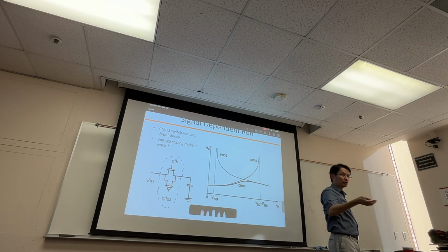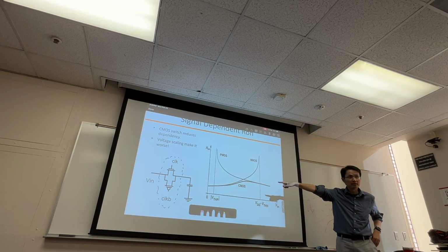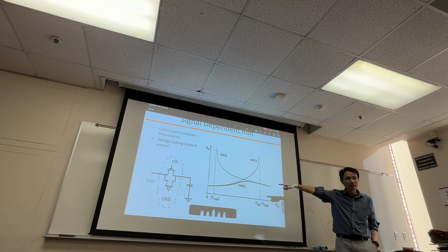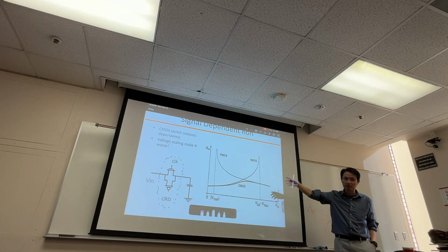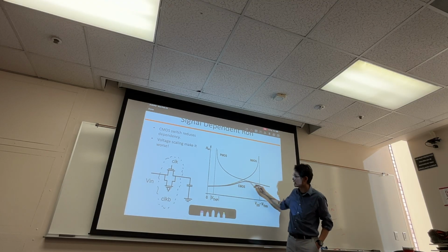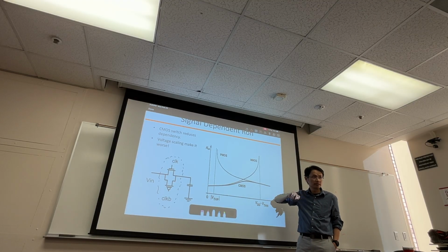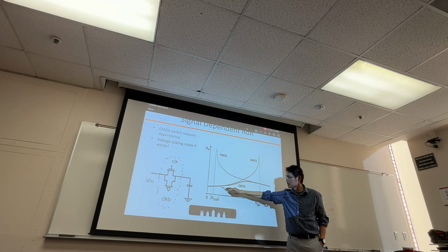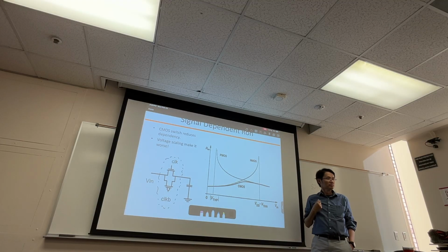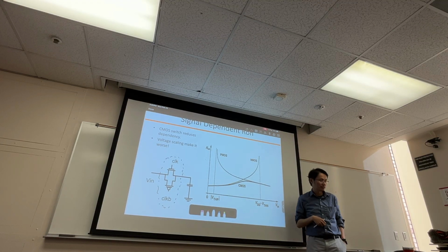Now the beauty of the transmission gate is you put two in parallel, right? So if I have a parallel resistance, one looks like this, the other looks like that. The composite resistance is here; you take whatever is minimum. That makes sense?